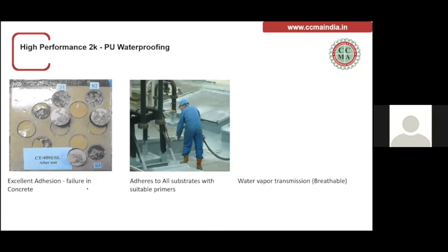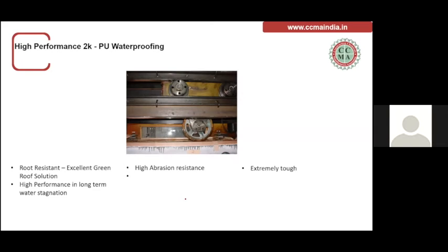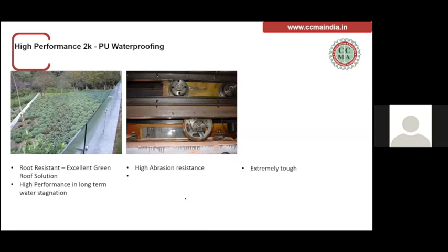Material can take any shape, any profile, and material can bond to any substrate. Yeah, it's spray applied. And then water vapor transmission. So if there is any moisture entrapped in the concrete, it is slightly breathable, and a certain amount of moisture can go out of the system without having any ballooning problems. It is root resistant, so it has passed various international root resistance testing.